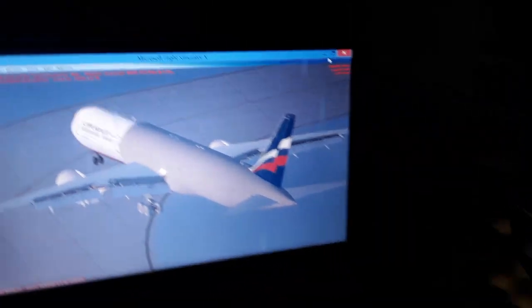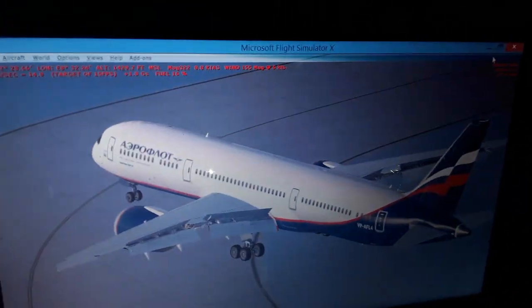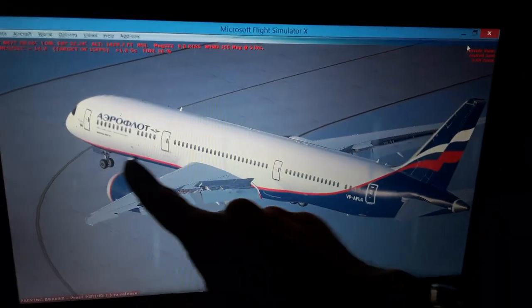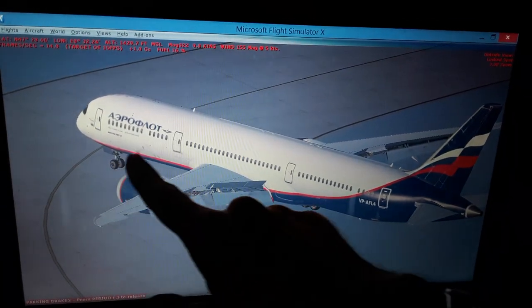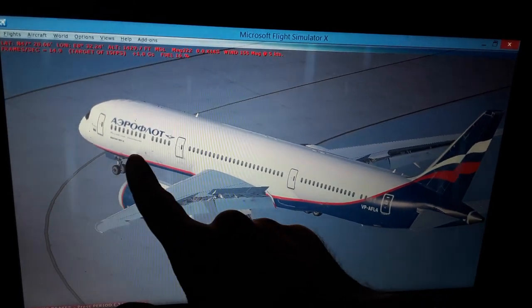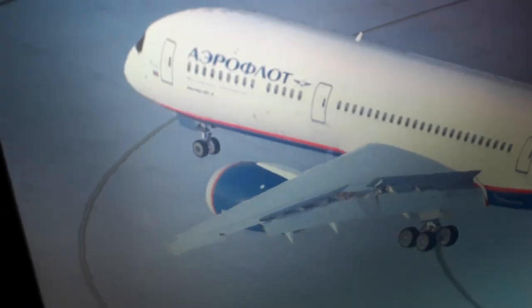So the nose wheel controls the yawing axis on the ground for takeoff, for example 76 degrees left and right, from 0 knots up to 45 knots, like 70 kilometers an hour. 76 degrees either left and right side deflection of the nose wheel.